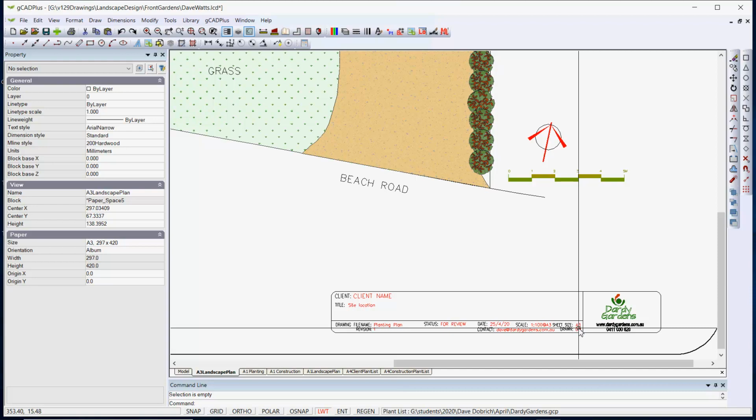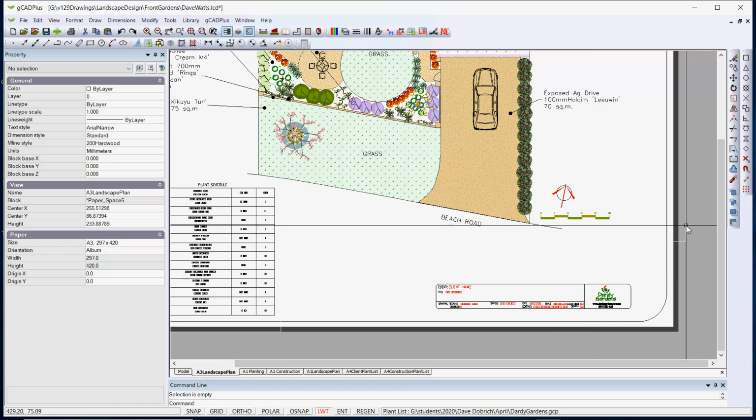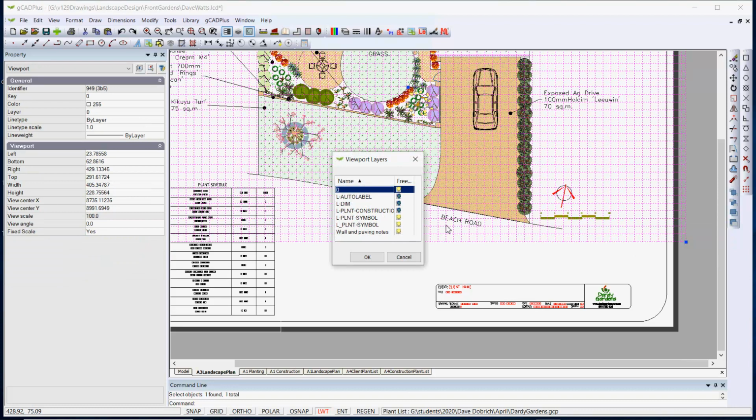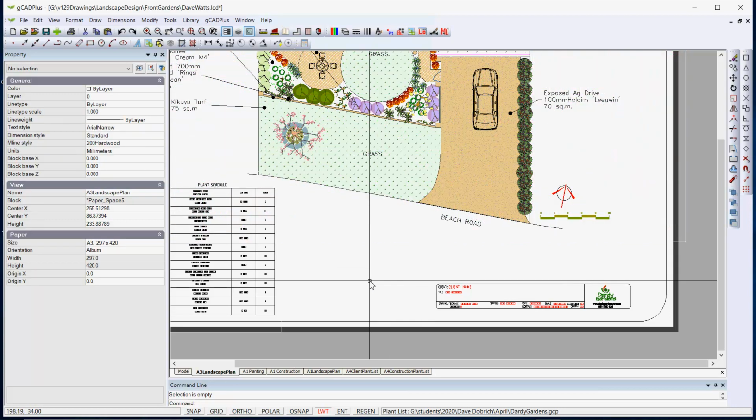And you might also add text to a drawing that you shouldn't scale off a drawing, that dimensions in the drawing take precedence. And what I've done here is I've selected this viewport and I've in fact turned off dimensions, but the dimensions are there, and I'll cancel from there and escape again.